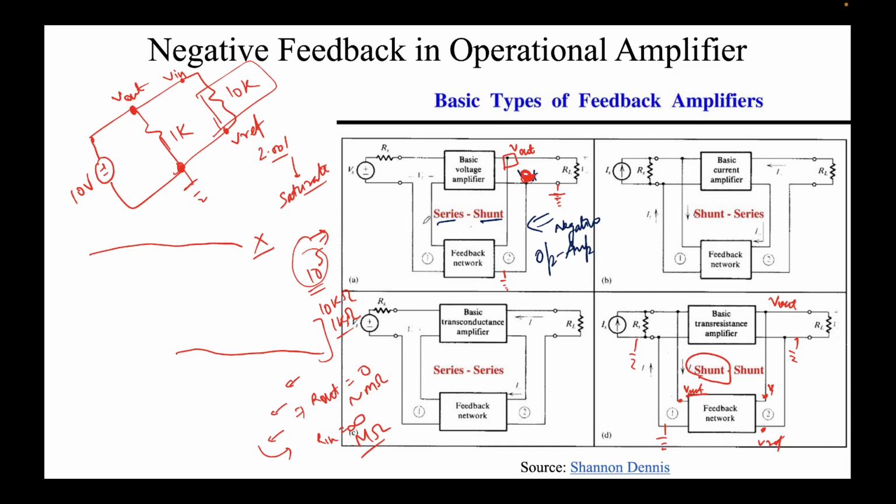In series, what we do is that we provide whatever the output is through usually a circuit of, if not a voltage source, then a resistor or something, which we see here. Every series thing, again, we'll solve using a problem. 10 volts. What is the current flowing through the 1 kilo ohm resistor? 10 volts by 1k, 10 milliampere.